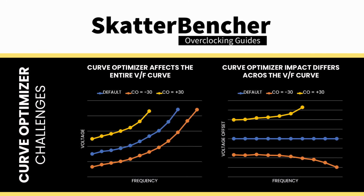First, Curve Optimizer impacts the entire voltage frequency curve, so it affects stability across a wide range of operating frequencies from 600 to 6000 MHz. The same curve optimizer value impacts differently across the curve. If you're lucky, your CPU's undervolt margin matches how Curve Optimizer applies the offset across the curve, and then you'll have a really easy time squeezing more performance out of your chip. But if the curve doesn't really match how the offset works, then it can become a little bit trickier to find the right Curve Optimizer value.